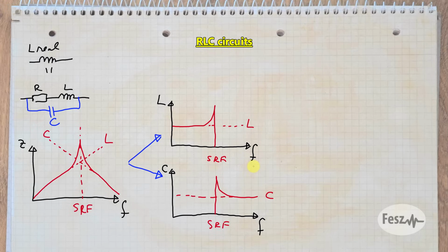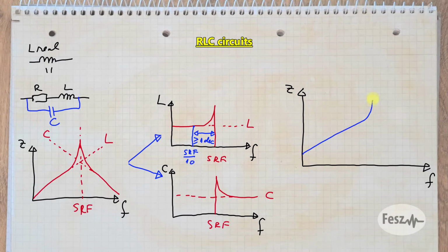So if you want to find the actual inductance of an inductor, you need to be well below the self-resonant frequency, by at least 1 decade. The other thing to consider is the fact that the capacitance of the inductor is dependent on the number of turns. If you have just one turn, you get very small amounts of capacitance, but also very small amounts of inductance. The SRF appears at high frequency values, but the impedance is quite difficult to measure at low frequency.